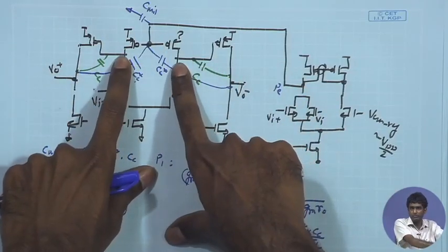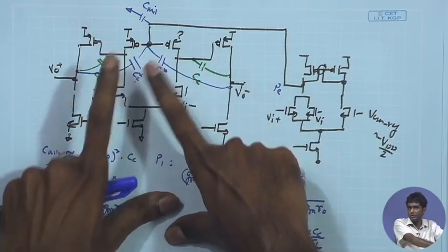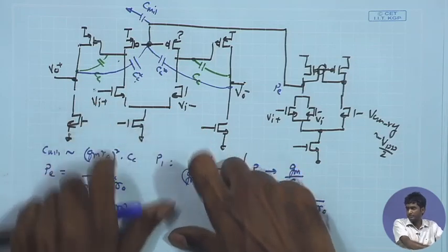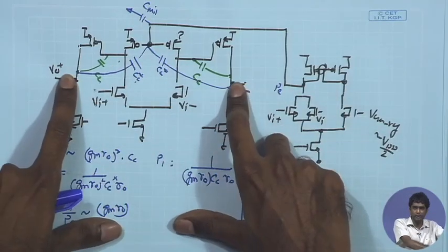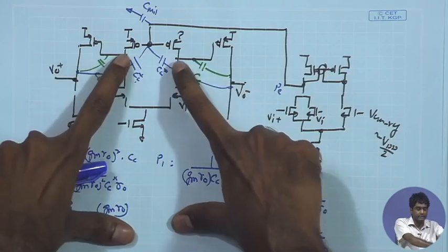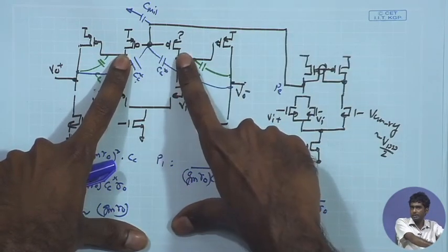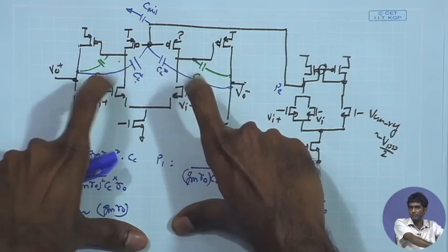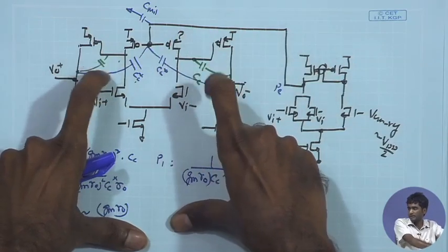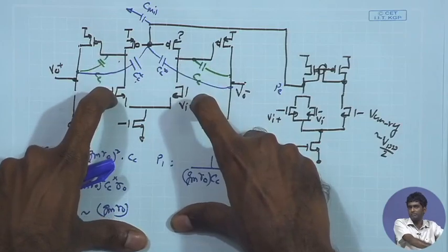You have a well defined voltage over here, which you are setting equal to a desired value. But when you are looking at only the output and you are allowing the feedback to set the value over here, this is only dependent upon the common mode feedback. It can go low or high depending upon the loop response, and then the first stage can end up being in trouble.